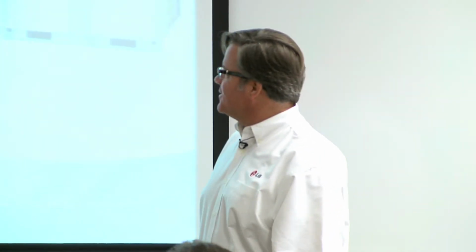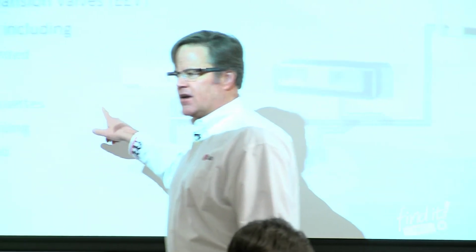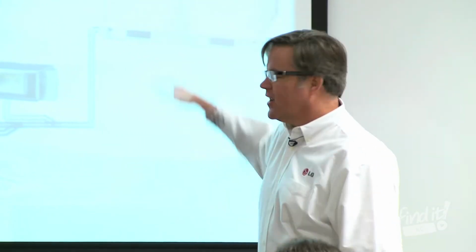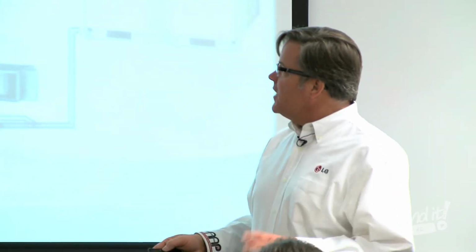So VRF, you're going to hear two terms in this market sometimes: VRF and VRV. They basically stand for the same thing: variable refrigerant flow or variable refrigerant volume. And all that's happening is we've got a gizmo outside that's kind of like your heat pump at your house. Some of the differences between this gizmo and your heat pump at home is you can connect to several different indoor units. But basically, this thing is a big glorified heat pump. So we'll try not to overcomplicate it any more than that.